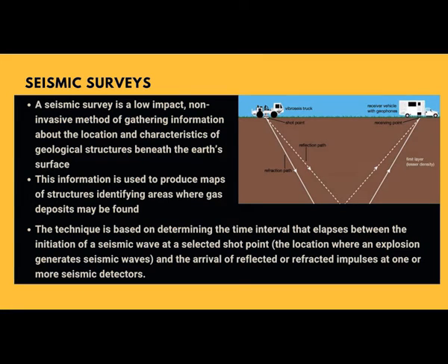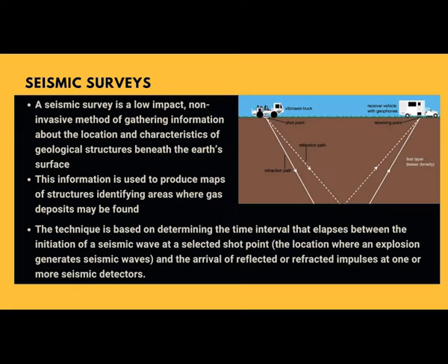Based on the time taken for the sound waves, we are able to figure out what kind of rocks are present. This technique is based on determining the time interval that elapses between the initiation of the seismic wave at a selected shot point, that is the location where the explosion generates seismic waves, and the arrival of the reflected or refracted impulses at one or more seismic detectors. This seismic survey can happen either on land or at sea. Different kinds of instruments are used, but the basic principle of operation is the same.